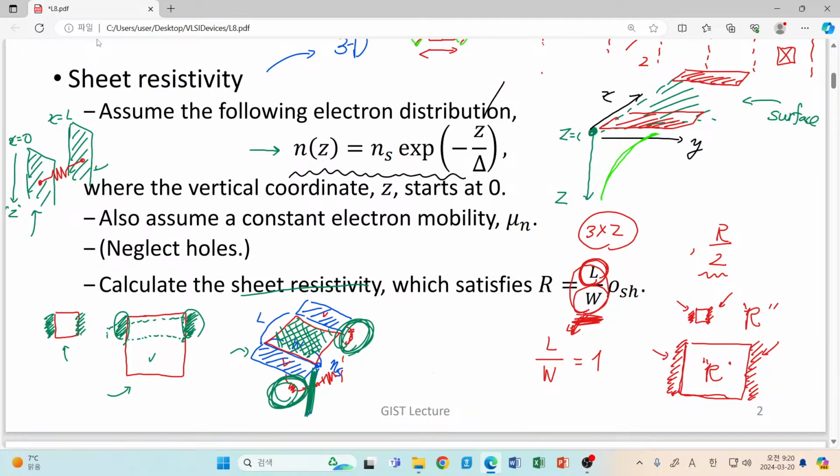Okay, so now you understand that the application area of this sheet resistivity is just squares, not the excess resistance of our contact region. However, in the usual case, that resistance is much smaller than the contribution from our long line.